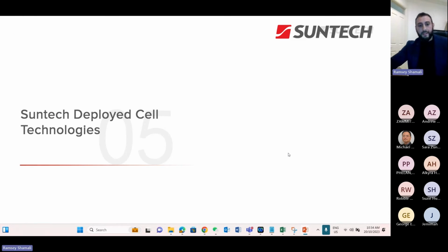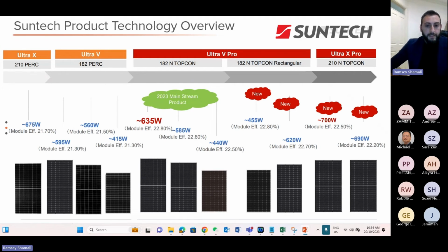So what is some of Suntech's deployed cell technology? What have we been doing? This is a portfolio overview of our products. You see we have adopted PERC for many, many years and still do to this day via our Ultra X and Ultra V products. In the Ultra X, it adopts the largest current cell format available today, which is 210. And Ultra V is adopting the 182 square format. So these are the range of different models represented here by the pictures and associated power class.